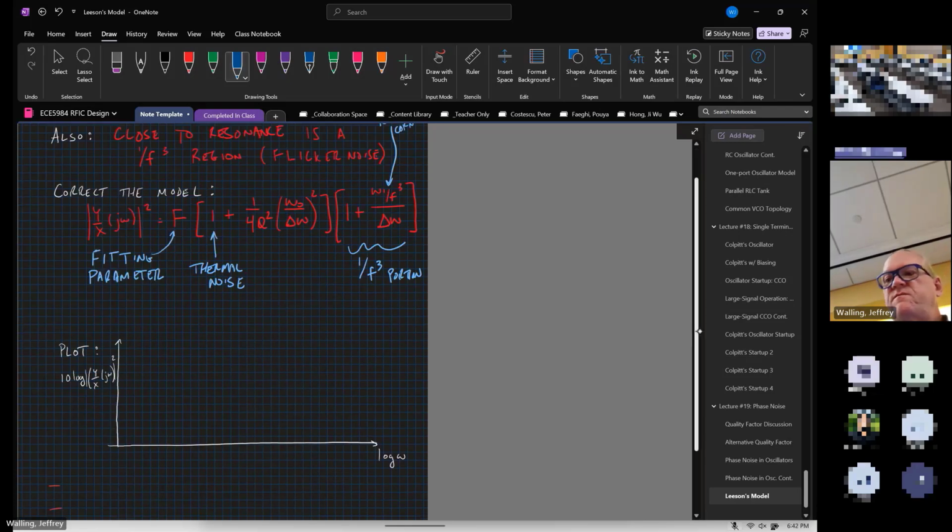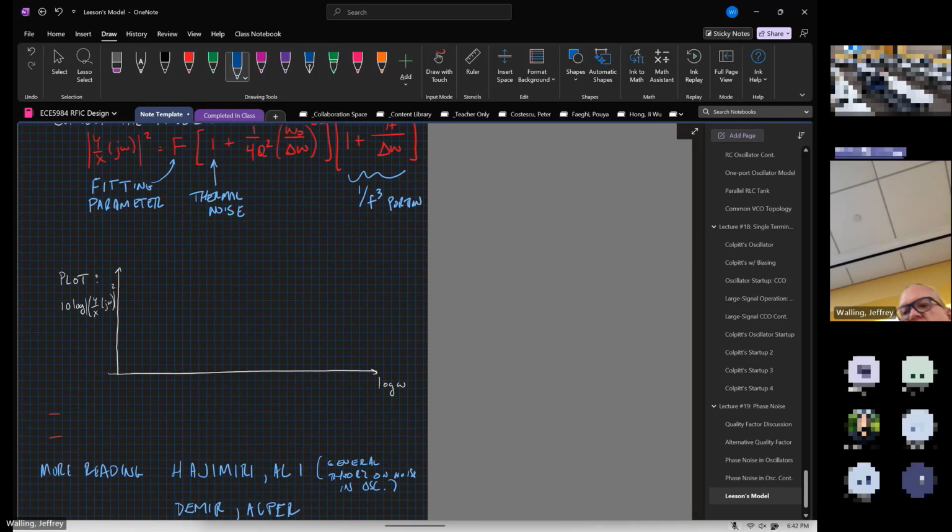All right, so what does phase noise look like in reality? If we measure this with an instrument, and our lab in Mix had a very nice one of these a few weeks ago that we got to test out. You'll see that there's a shape where you get a minus 30 dB per decade roll off of the phase noise.